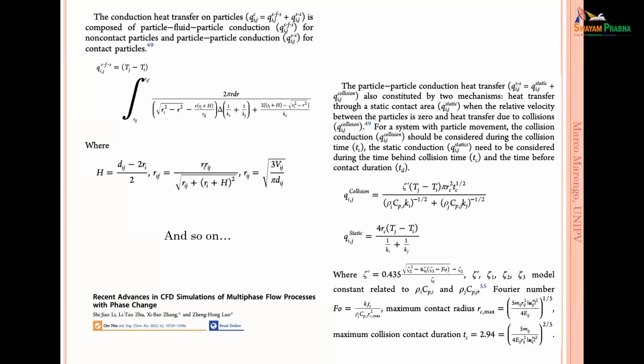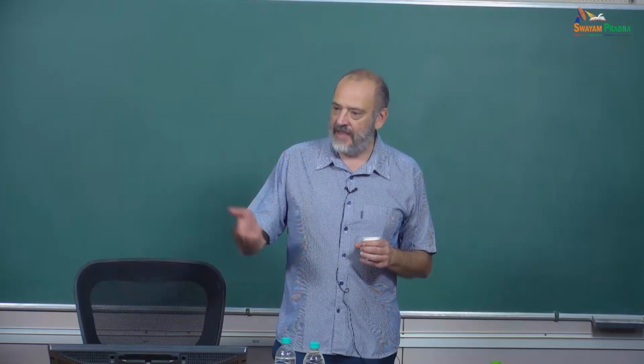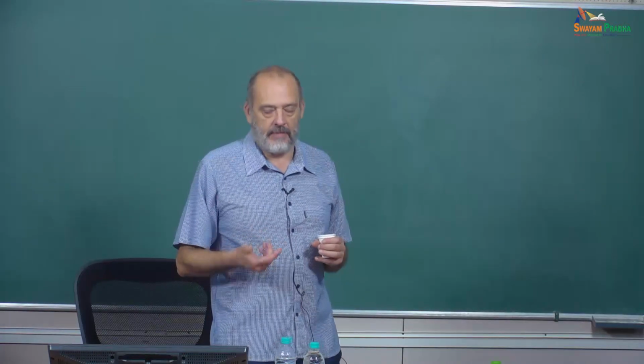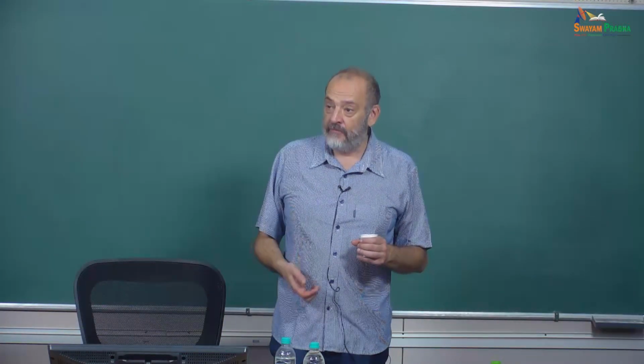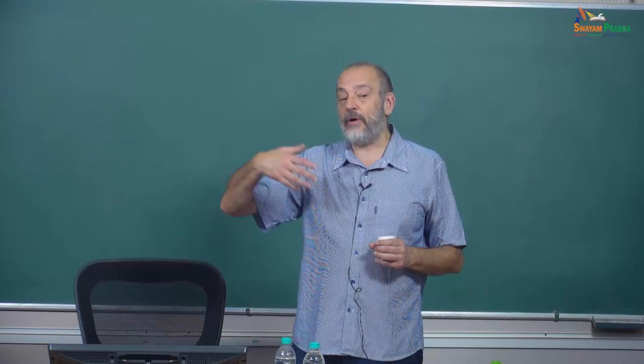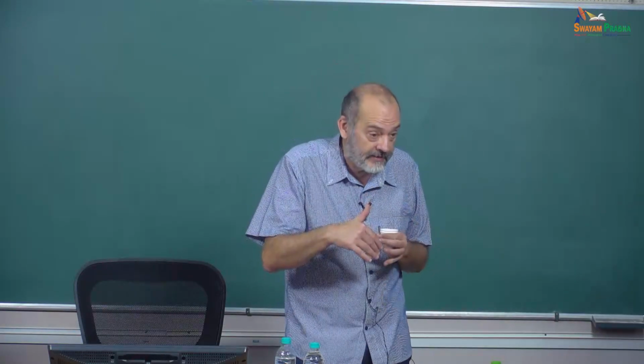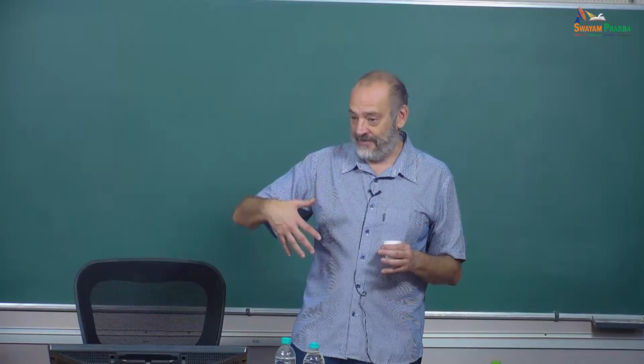If you want to read more, there is this paper from 2023, because this is part of research now. One can think that it's consolidated and everybody knows how to deal with this, but it's still research. As I said, all these coupling forces, coupling energy, heat going from one phase to another, is a question of tuning in many cases. So it depends on the material, for example the conductivity of the particles, and how we can deal with the conductivity of the parcels, because the parcel contains many particles, maybe with different conductivities, because we don't have only one solid particle, maybe we have different components of the solid particles.